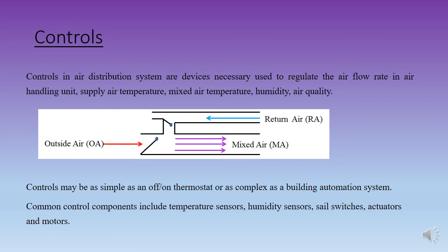There is no 11 inch, for example, duct size. The only odd number for duct size is 3. We have 3 inch, but other than 3 inch we don't have any odd number for duct size. We have 4 inch, 6 inch, 8 inch, and so on.